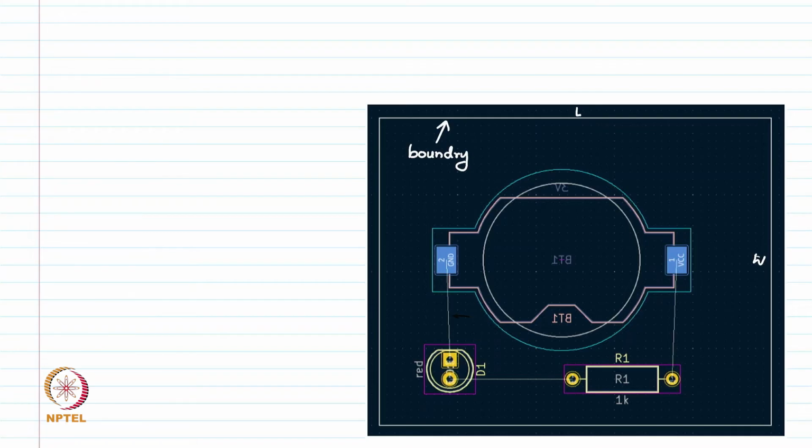So we put a via to prevent that misconnection. The number of vias will be equal to the number of crossings of the rat nest, and we want as few vias as possible, because they increase the complication in PCB design. So in this step we need to place the footprints.